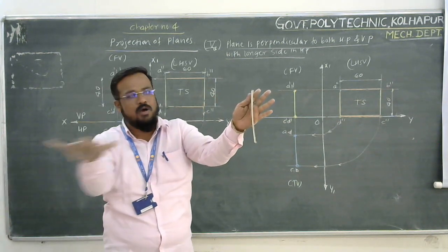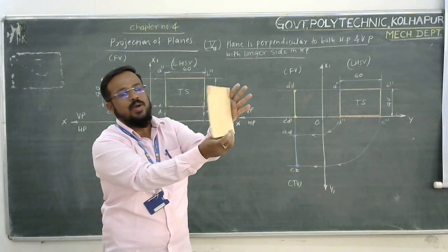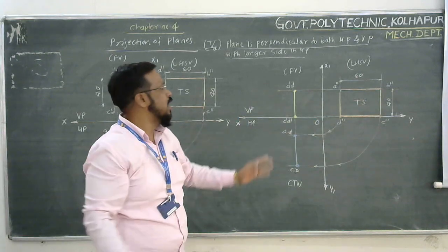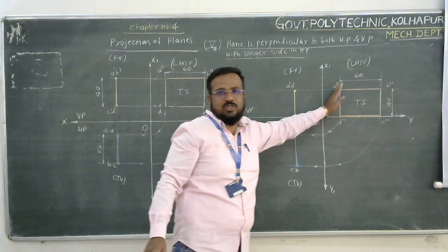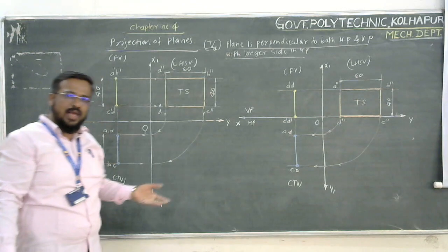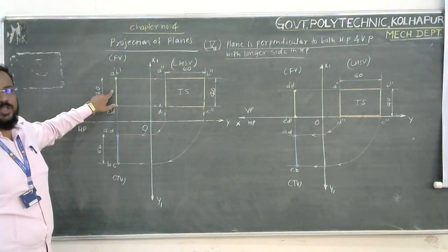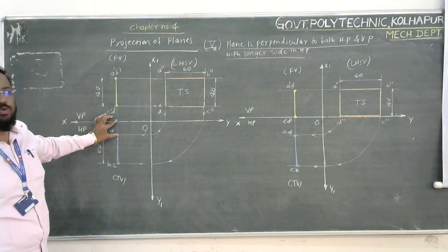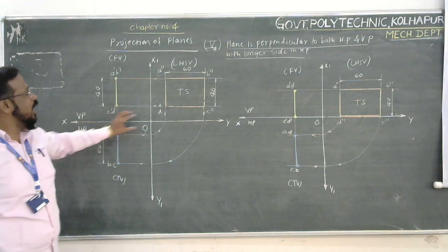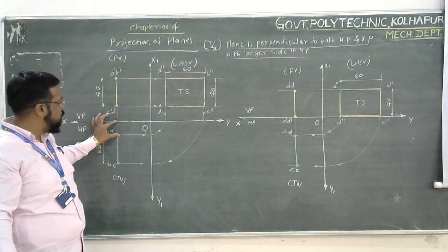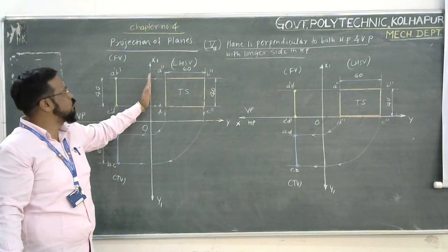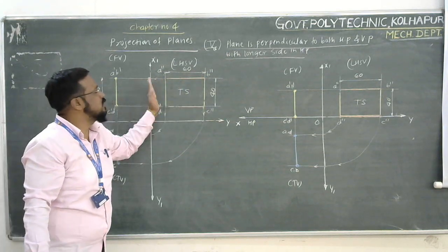So when a person observes from this side view, what will happen? If I rotate its side view, see, it has its position exactly adjacent to this X1 Y1 plane. So now it is clear, with this projection, there will not be a change in the front view. There will be a change in the top view. This distance is going to be equal to 0, and in the side view, as this B distance has become 0, remember, we have turned it, that is, this B has to be 0. So immediately this plate has to start its shape from this X1 Y1.